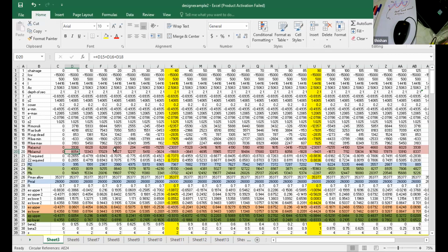When the moment range increases, the pre-stressing force and all the other things will also increase slightly. But it's no harm, because now we have taken the practical construction sequence into account when doing the calculations.